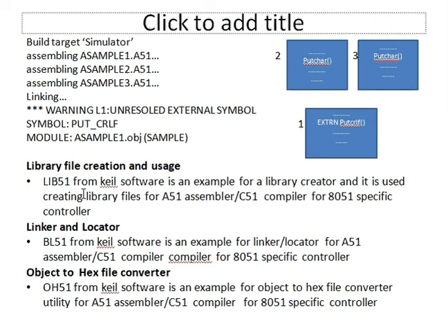Hence, for hex key, we will create a library, and we will put all the essential configuration methods, initialization method, command and data for LCD, to enable LCD, everything under a file, and we will include that file into our hex key program, so that the size of your hex keypad interfacing program becomes shorter. So we will see how it can be done at a later stage.